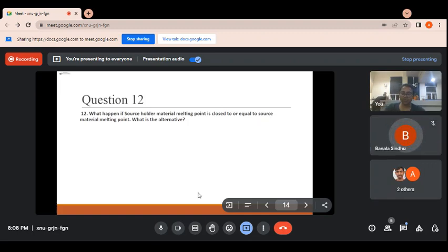Okay. Actually, what happened in isotropic etching, there are two basic types of etching process, like the dry etching process and the wet etching process. In the dry etching process, we use some gaseous molecules or plasma to etch the substrate. In the wet etching process, we use some chemicals, like for silicon etching, we use the TMAH process or KOH-based solution.